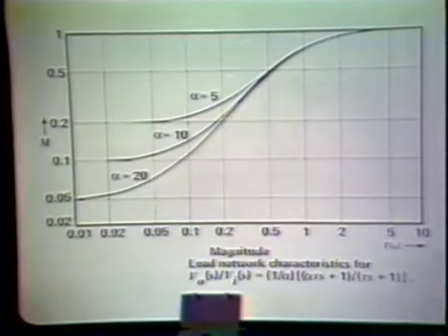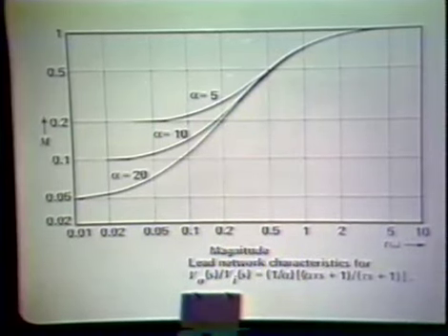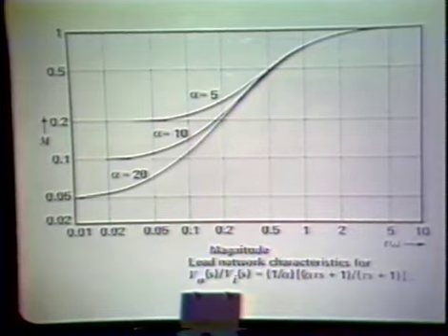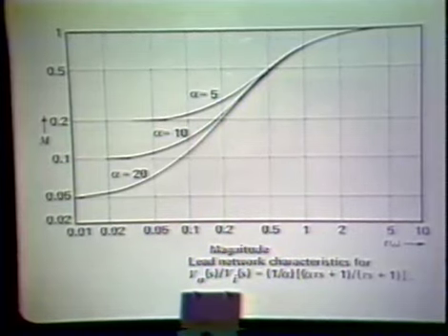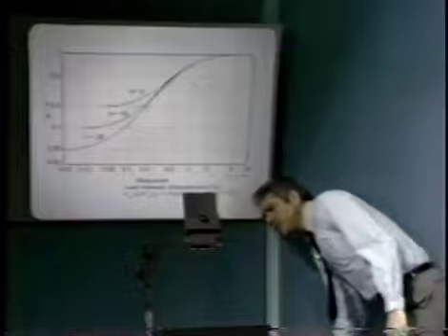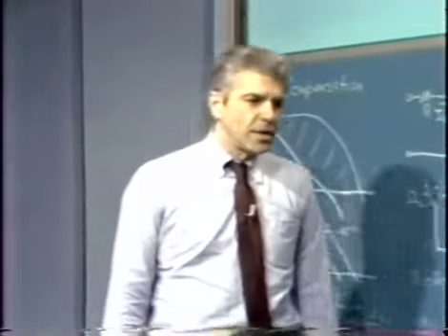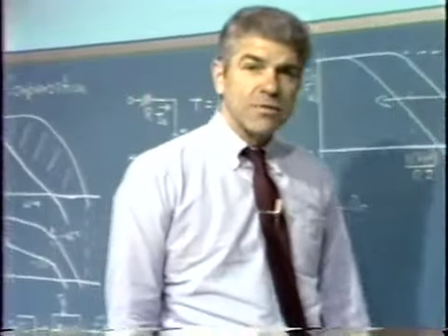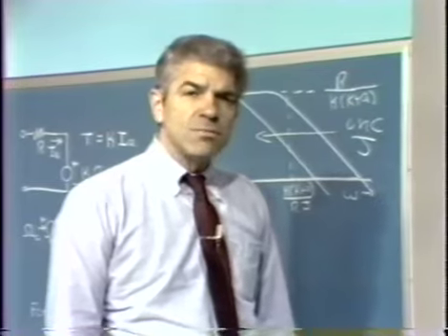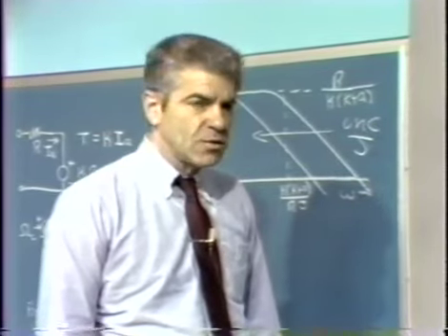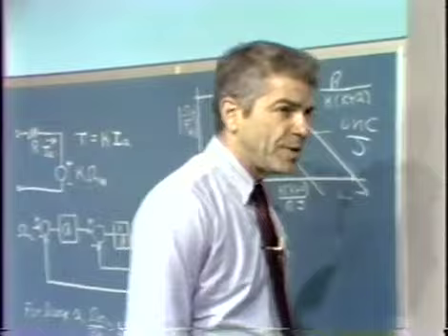So the important part about the lead transfer function, or at least one of the properties of the lead type transfer function that we're able to exploit, is the fact that the phase shift becomes positive by a very significant amount, at least in terms of improving the performance of a feedback system, before there's much change in the magnitude characteristics, and we can use that. And the way we use it is as follows.